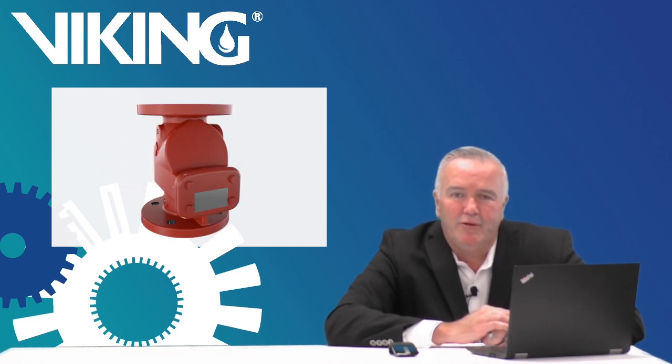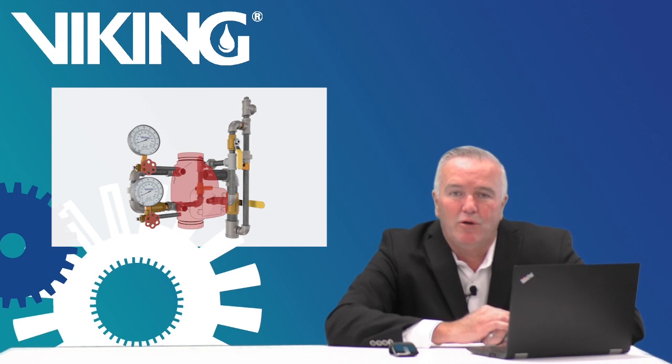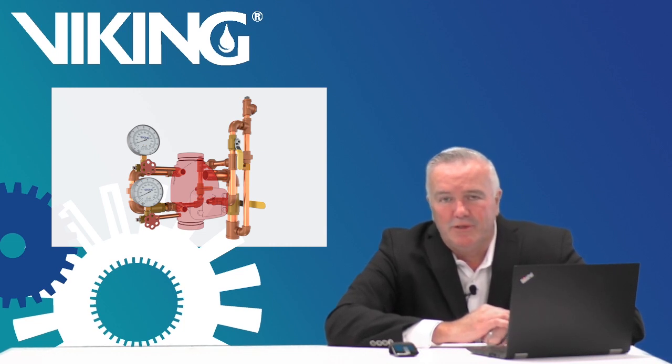And if you've ever put together a valve, especially a complicated valve such as deluge, double interlock, or something along those lines, there's a lot of parts and pieces that go to make it a whole valve. And getting it correct, getting all the right components, getting all the right part numbers is a difficult task. And my history, starting off as a design trainee, I spent a lot of time reading data sheets, trying to figure out how all the components bolted together so that I could understand and explain, if the field ever called me, how it would activate, how to reset a valve, or how to troubleshoot a valve.